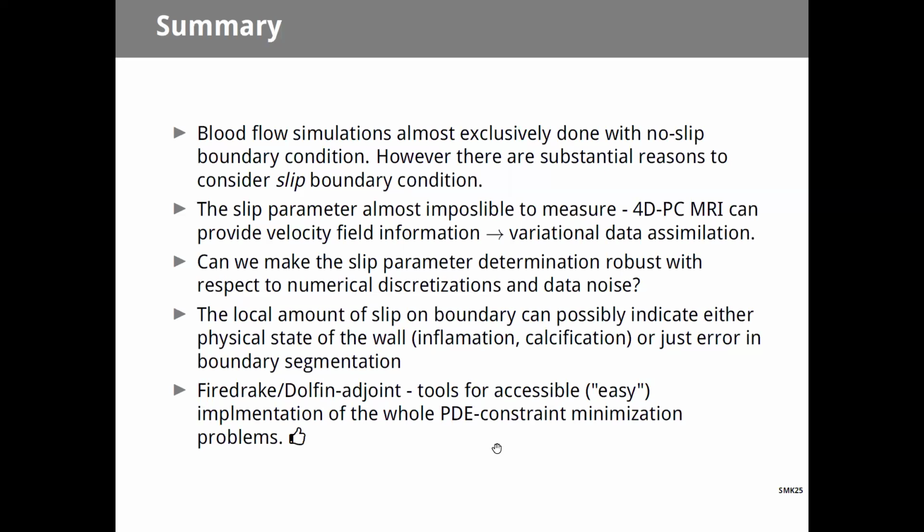In this case, they were able to group the results, as I said, with this ANSYS software. The boundary condition was not given exactly, it was given in terms of flux. So some people used a parabolic profile, some people used plug flow, and that made two distinct groups in the results. That was basically the outcome of this test.